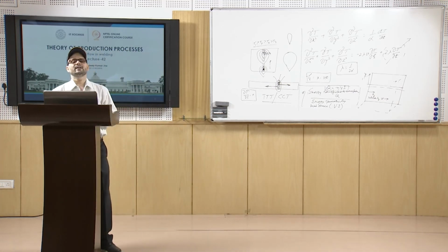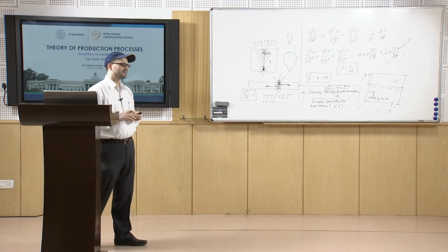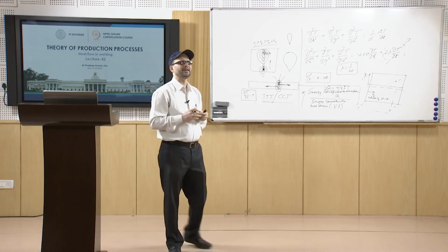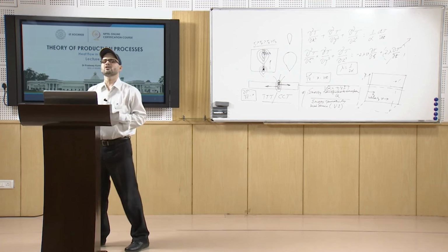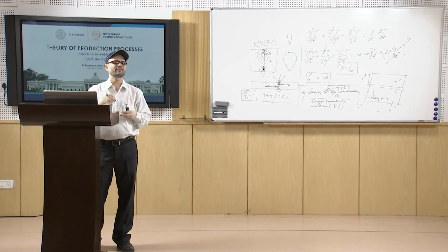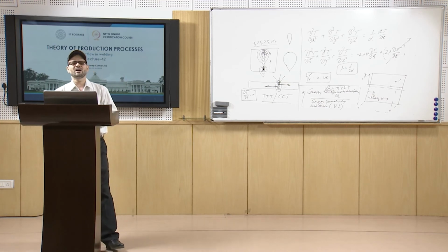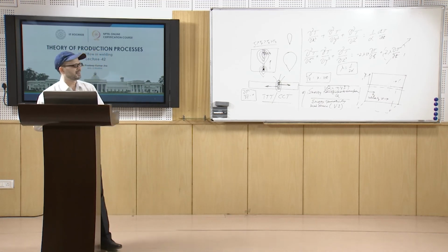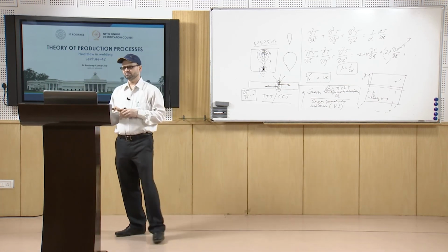Or if you talk about electron beam welding, this has a very high thermal efficiency, which may go close to 100 percent. It is because of the keyholing phenomenon: it makes a hole that works as a black body type of property.